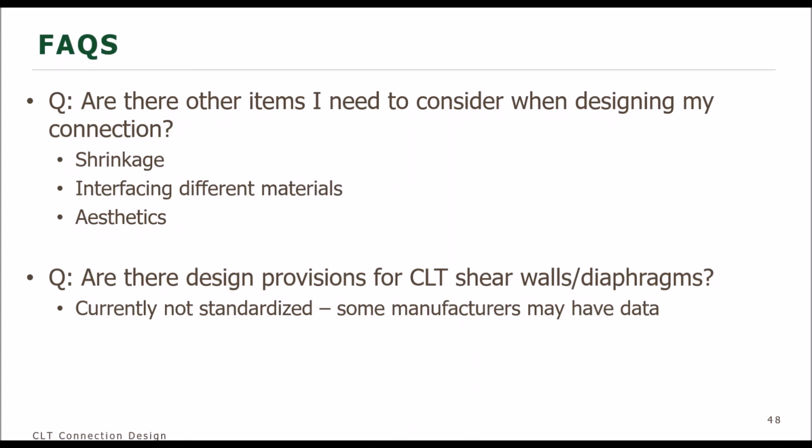So when we look at smaller fasteners, especially in terms of that geometry factor, the C sub delta factor, the line gets drawn at a 1/4 inch. So fasteners that are on the smaller end, less than a 1/4 inch, we don't have to calculate that geometry factor. For larger diameter fasteners, the geometry factor calculation is necessary. So it's not necessarily codified, but that's kind of a rule of thumb. And obviously, it's going to be relative to the dimension of the wood that's being installed in as well.